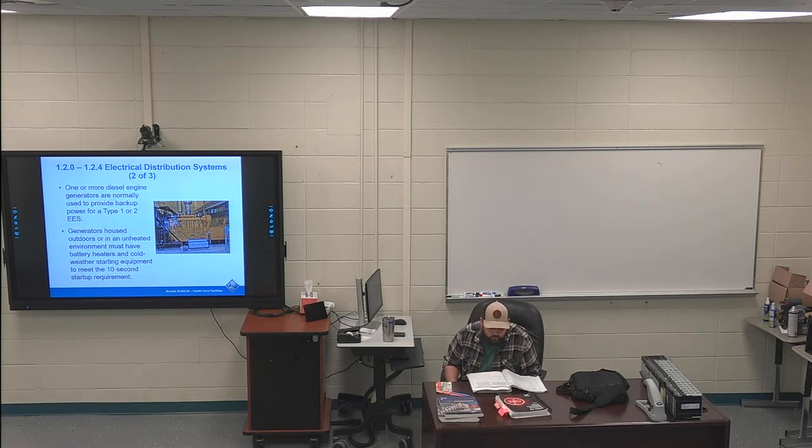Page 9, 124, additional grounding and bonding requirements. Second sentence is highlighted. As specified in NEC section 517.14, where branch circuit panel boards for normal and essential power serve the same patient care vicinity, they must be connected together with insulated copper conductor no smaller than 10 gauge. Another question to come out of that.